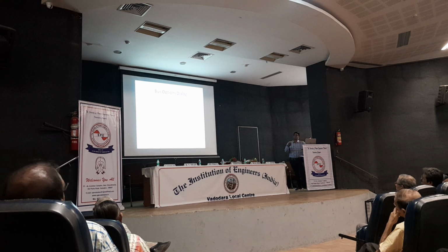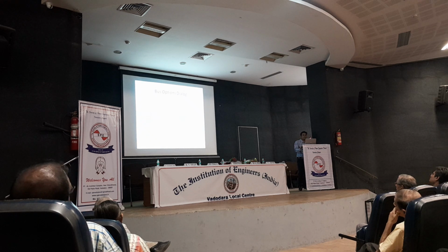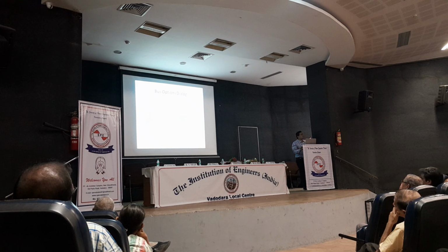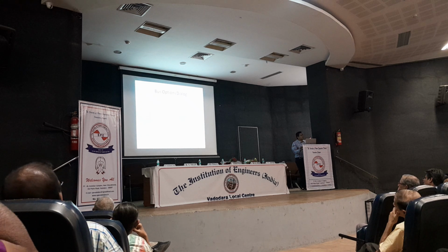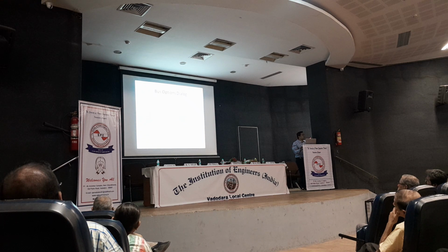When we select the bus from the draw option, one dialog box will appear. It will look like this. If you pay attention, you will find bus number, area, zone, owner, substation, everything we can define nicely. At the bottom, you will find bus information, display, attached devices, geographical conditions, and custom things that can be added if we want further details. But for the simplest case, we just select the bus information and enter the bus voltage.